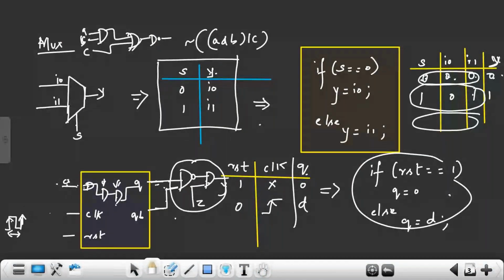They can only tell that if my input is 0 when the positive edge of the clock comes, 0 will go to the output. Only they can verify that. But whether it will go within one clock cycle, they cannot assure. That is assured only after this program is converted to the gate level. So it happens only in synthesis, right?